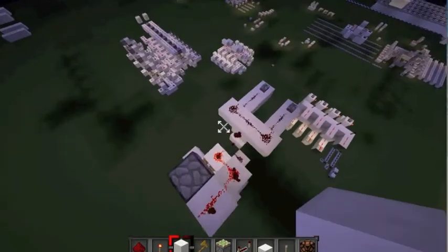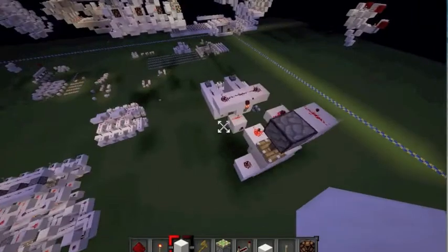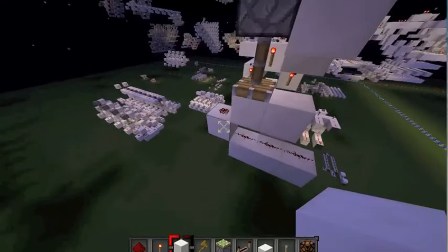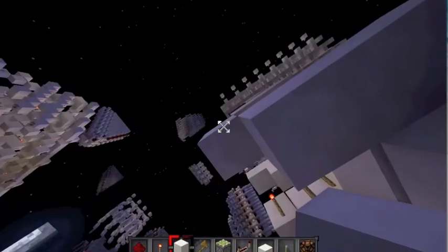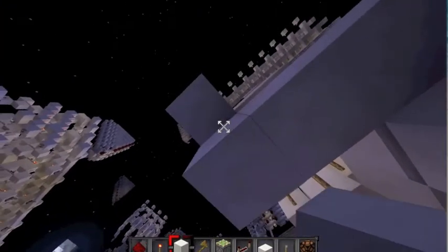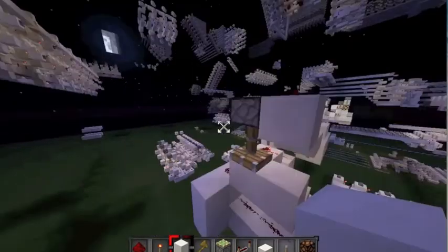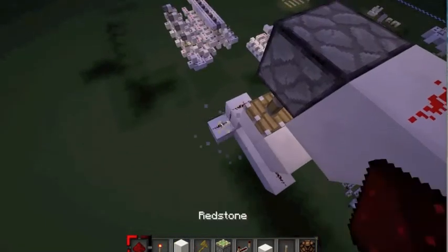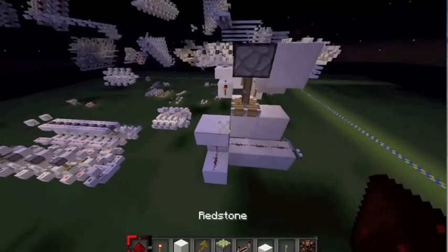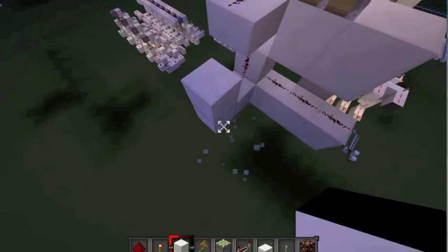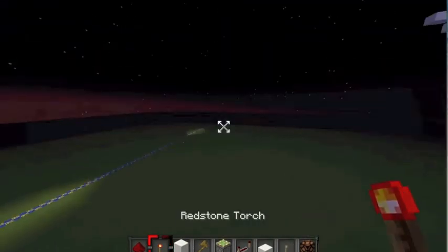So yeah, this is basically the first half adder that I am going to end up building. For the second half adder, I'm just going to be using the, no, not the Tommy's XNOR, a multiplexer based XNOR. And the reason that I'm going to be doing that is I can actually do a bit of a swivel with it to save space in this direction.